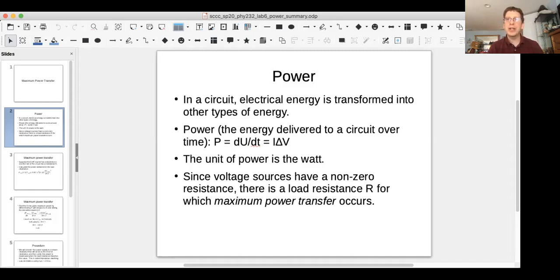And your voltage across the 1,000 ohm resistor turned out to be higher when they were connected in the same circuit. That's because the greater resistance is going to take a greater share of the potential difference, and the remaining potential difference is lost inside the internal resistance of the power supply.